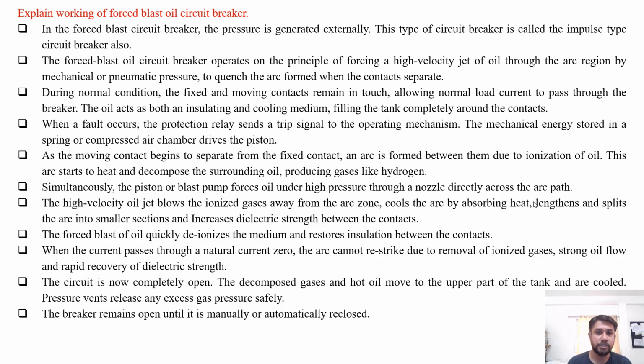During the normal condition, the fixed and moving contacts remain in touch like this, allowing the normal load current to pass through the breaker contacts. The oil acts as both an insulating medium as well as the arc quenching or say cooling medium, filling the tank completely around the contacts. Now when a fault occurs, the protection relay sends a trip signal to the operating mechanism. The mechanical energy stored in the spring or the compressed air chamber drives the piston in downward motion.